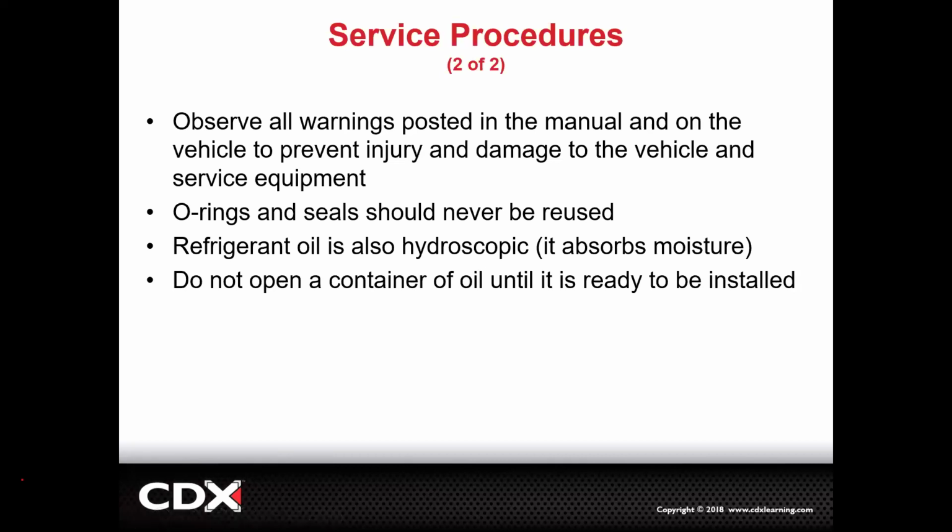Refrigerant oil's hygroscopic. What that means, same as brake fluid, is you can't have refrigerant oil just sitting out chilling. It's going to absorb moisture. We have it absorb moisture really to keep it out of the refrigerant flow.